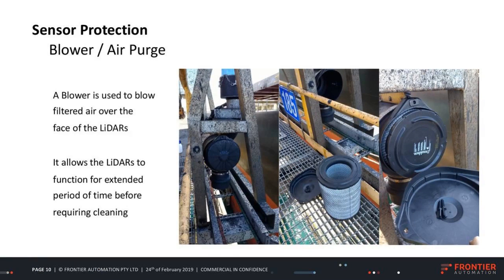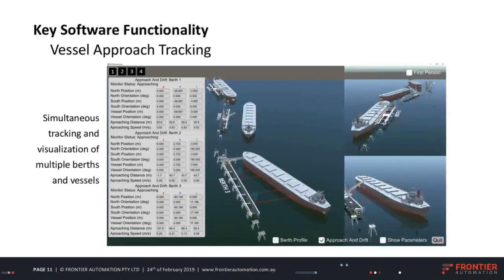The in-house engineered protection that we build around these sensors, in these more recent installations, includes pre-cleaning, filtration, and an air blower to create positive pressure in the housing. What that all means is you can install this in very challenging locations, even offshore, where the sensor potentially never needs to be looked at, or at least is checked once a year, and that's about it.